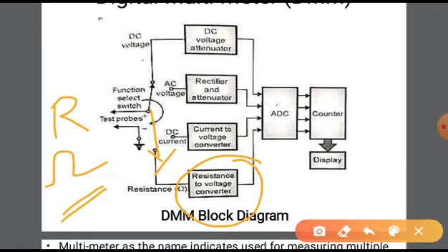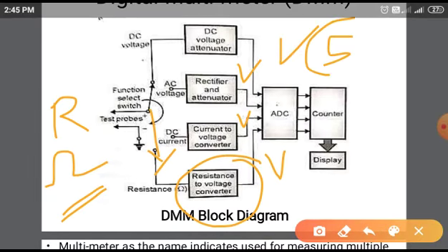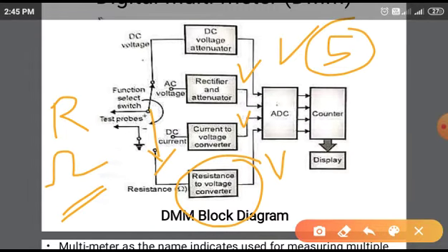The unknown resistance goes to some resistor divider. For example, you can use the Wheatstone bridge. When the bridge is balanced, the output is 0, and when the bridge is unbalanced, the output is directly proportional to the unknown resistor. That means voltage is our output. In general you require 5 volts at the ADC input.